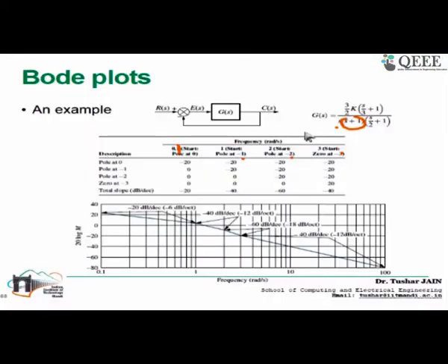First we write all the poles and locations here, and we start at 0.1. Let's say the start pole at 0, then a pole at -1, -2, and -3, and all the frequencies are associated with it. These are nothing but the frequencies, right? If you write s equal to j omega, these are the frequencies associated with this function. We were recalling how we can draw a Bode plot for this given transfer function, and the same principle you can use to draw the Bode plot of other transfer functions as well. First, we identify all the poles and zeros, and these are the breakaway points.